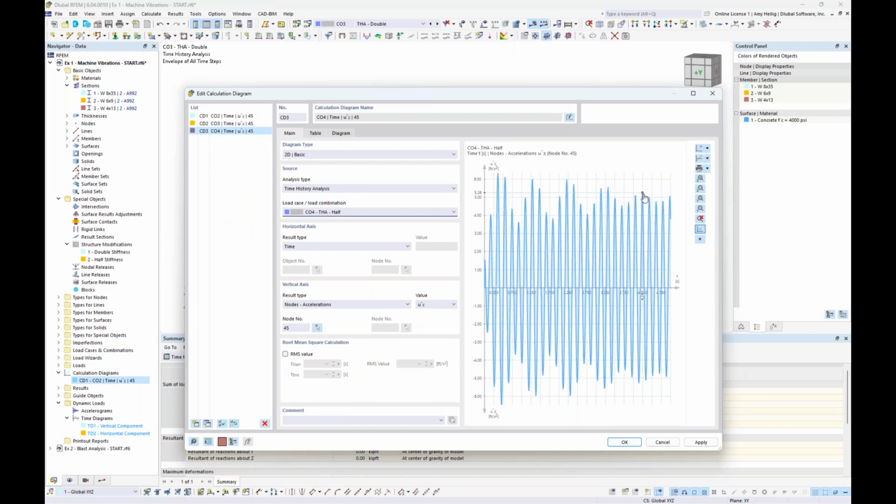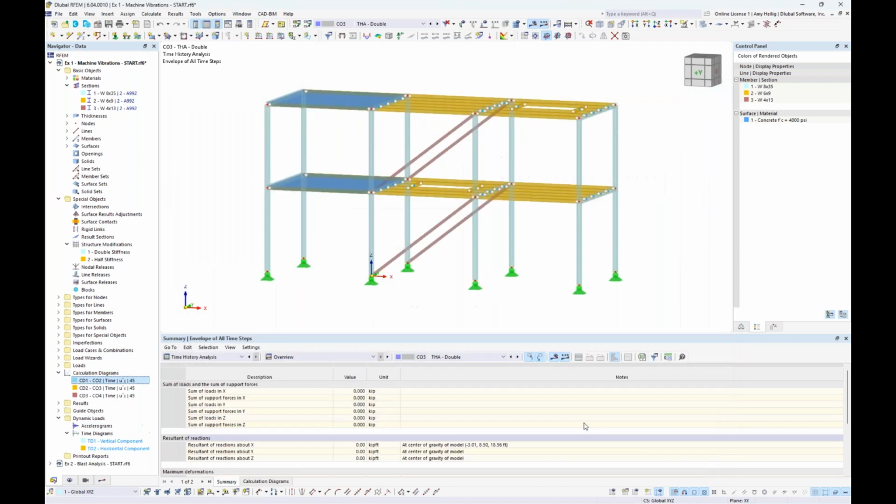However, we do need to still take a look at the total acceleration values, a little bit higher here, around 4 to 5 feet per second squared. So it'd be up to you as an engineer to determine, okay, is this within the allowable range, or do we need to make further modifications? But once we have an idea about the general stiffness options based on those factors, then we can go in and make modifications to that W shape.